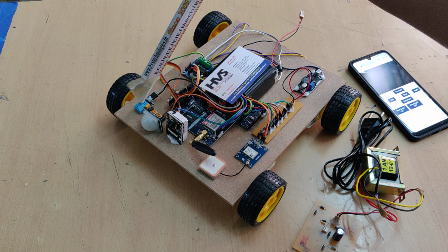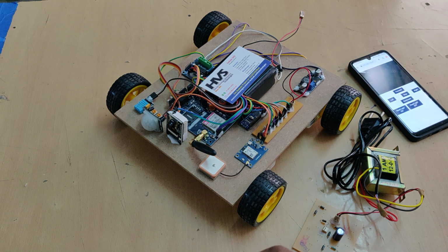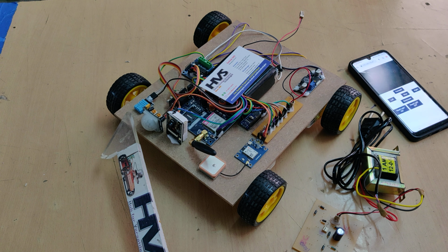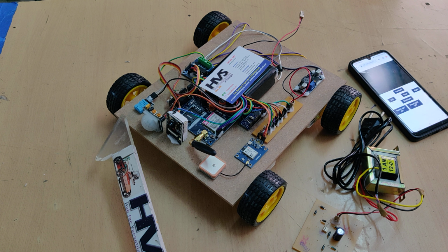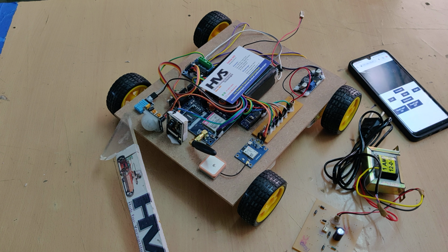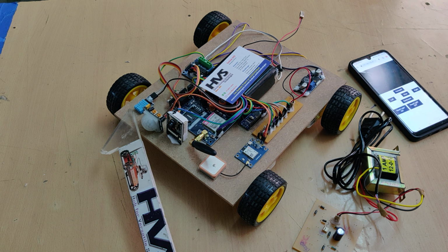from this DHT11 sensor. The next two alerts are high humidity, whenever the humidity level is above 75%, it will send the message alert along with location and the parameter values, and when temperature is above 40 degrees centigrade, it will send the same message alert.